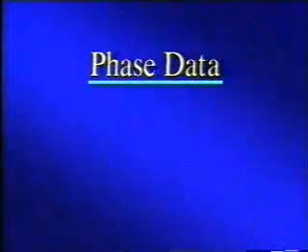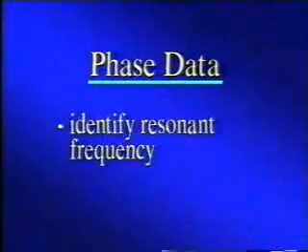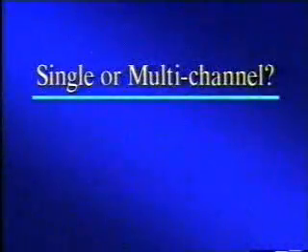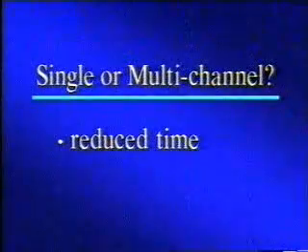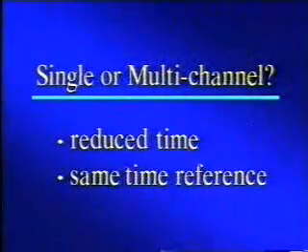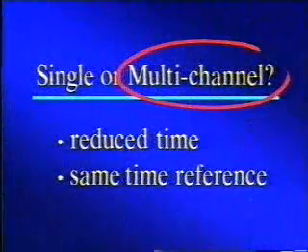The phase data provided the ability to identify the resonant frequency and the source of excitation. These measurements could have been taken with a single channel analyzer. However, the reduced time to collect the data and ability to have the same time reference for the comparisons made the use of the multi-channel analyzer the tool of choice.